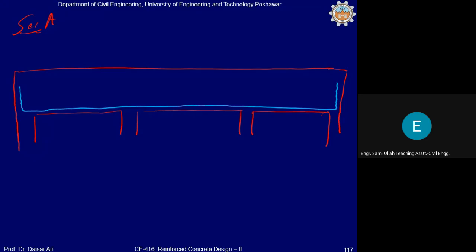And this reinforcement will be given closer to the bottom face, as you know. This is number 4 at 6 inch center to center. Okay. Similarly, the bottom reinforcement along the longer direction will be denoted by these dots.